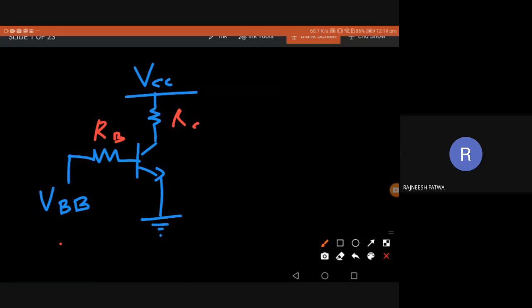So are you able to get it? I'm getting one answer and two answers. Yeah, two answers. This circuit is actually beta independent. Why? Let's calculate the Q point. When you calculate the Q point, you get that there is no dependency on beta in those equations while calculating IC and VC. Okay, so this is beta dependent.